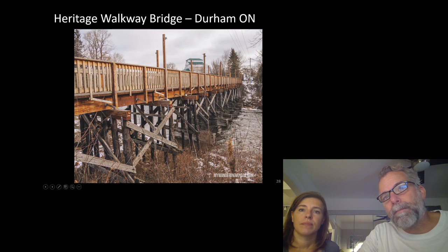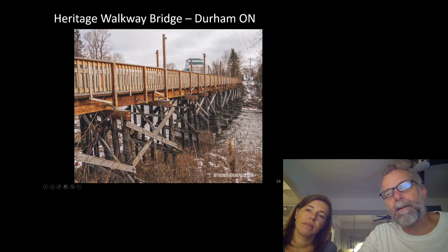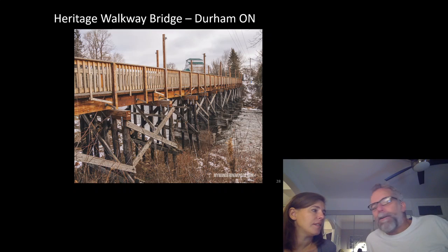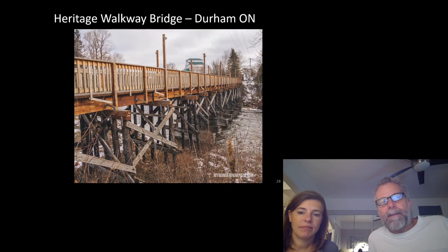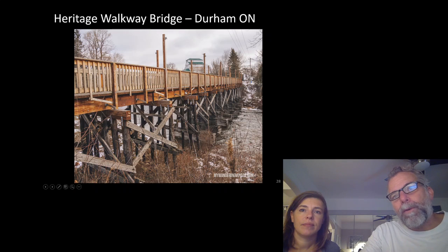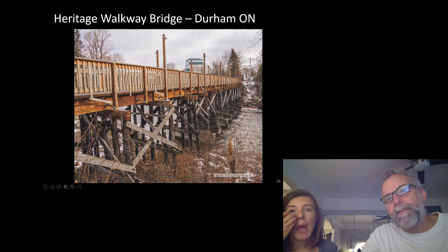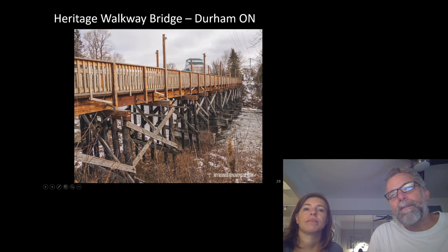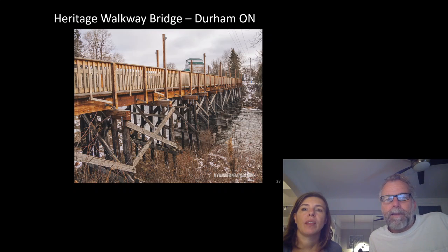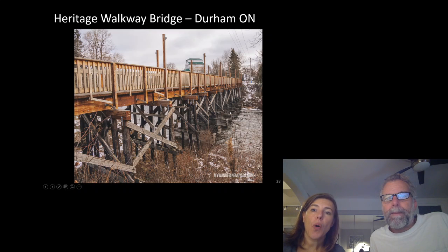And so we do a trestle bridge, and the advantage of a trestle bridge is very short spans. If you remember Shannon's talk on one thing or another, the reason why we do trusses is to avoid bending, because axial loads are much more effective than bending loads. So if we can build up this base infrastructure and shorten those spans and avoid a big girder, then there's a real advantage to it.